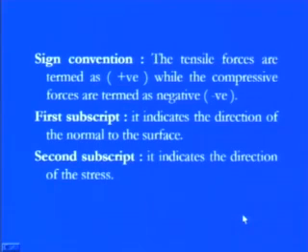So these two coordinate systems are well accepted universally. If the regular geometry is there, like a square or a rectangular bar, it's pretty easy for us to analyze those stress components in Cartesian coordinates. But if we have curved surfaces, like an aerofoil or any radial geometry, a turbine blade or aerodynamic blades, then we always need to choose the cylindrical part, the polar coordinates.